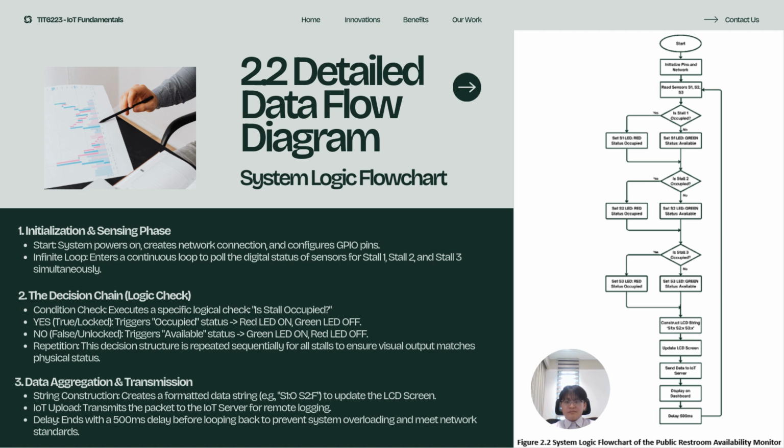This code executes a specific logical check on each stall to see if it is occupied. So if the condition is true, which means that the lock is closed, then the logic will follow the yes path. It triggers the occupied status, turning the red LED on and the green LED off. If the condition is false, which means that the lock is open, then the logic will follow the no path. It will trigger the available status by turning the green LED on and the red LED off. This structure is repeated for every stall, ensuring the visual output always matches the physical reality.